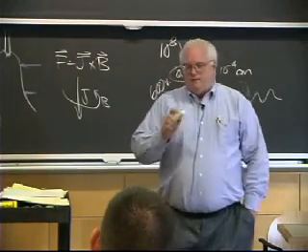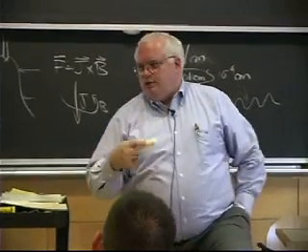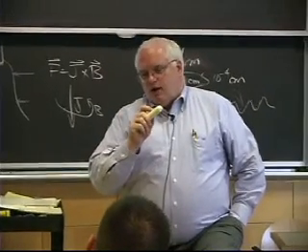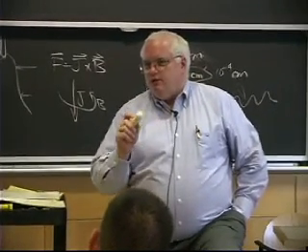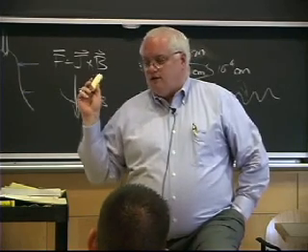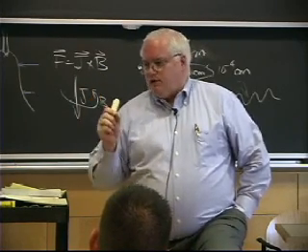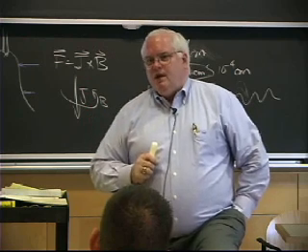Well, it turns out by doing single point diamond machining, aluminum has always got some inclusions in it, and I said, well, maybe you're getting field emission because you're almost at 1,000 volts and you've got a thickness that's on the order of the right type of thickness to get field emission.